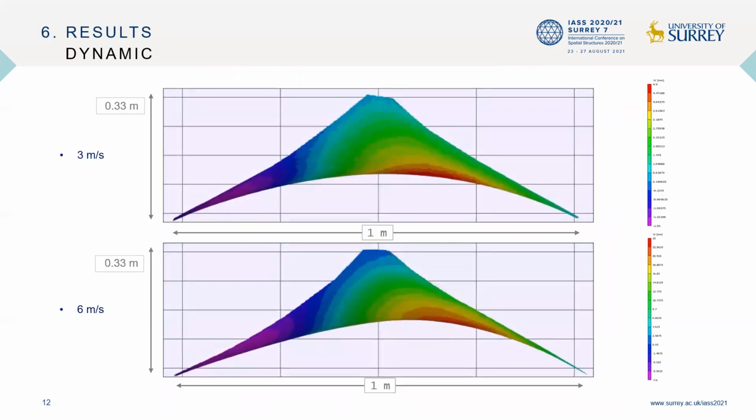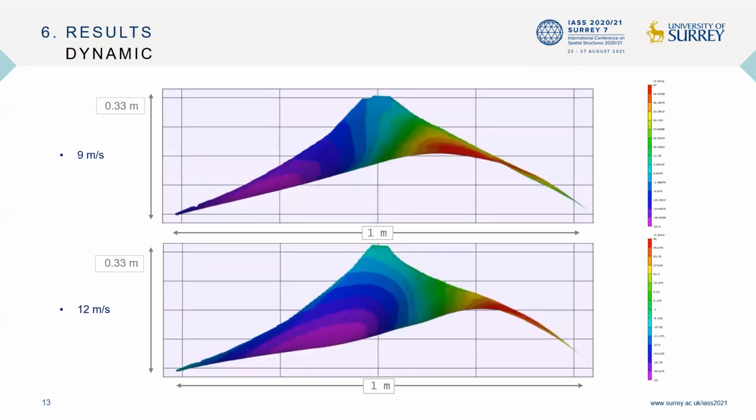By understanding the workability of the DIC system, after going through different stages of study, positive outcomes were achieved during the measurements in the wind tunnel. Proportional behavior could be observed, and movement along the increasing wind speeds could be related to a theoretical as well as physical reality. Small deflections as well as dominant deflections were well visualized by the DIC software, with clear zones of influence being divided along the surface.